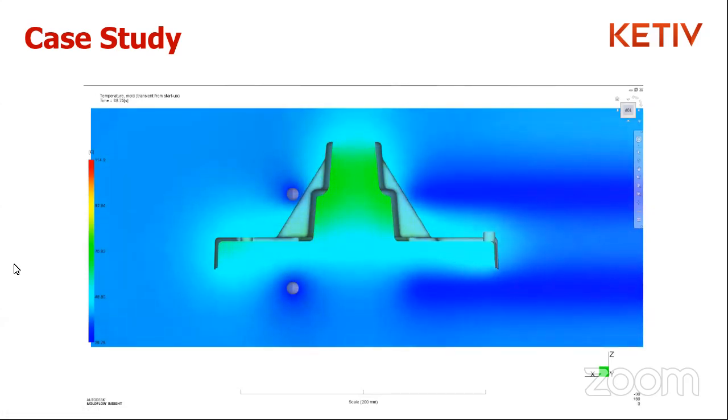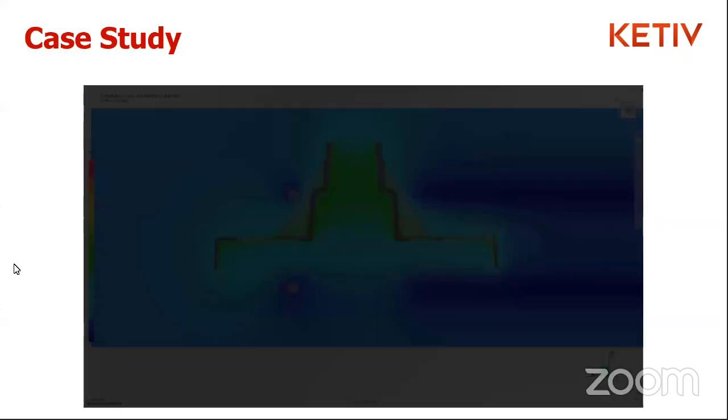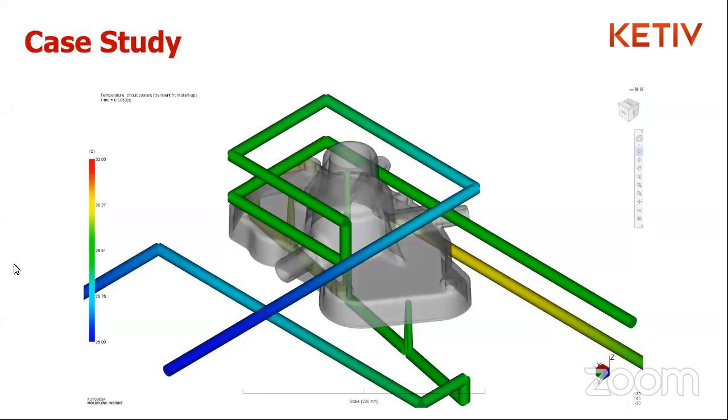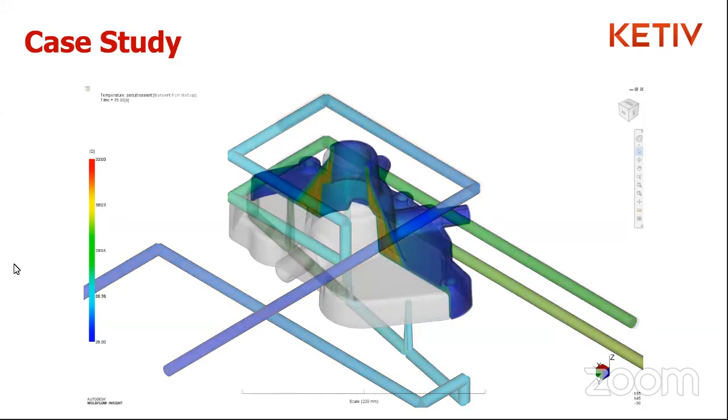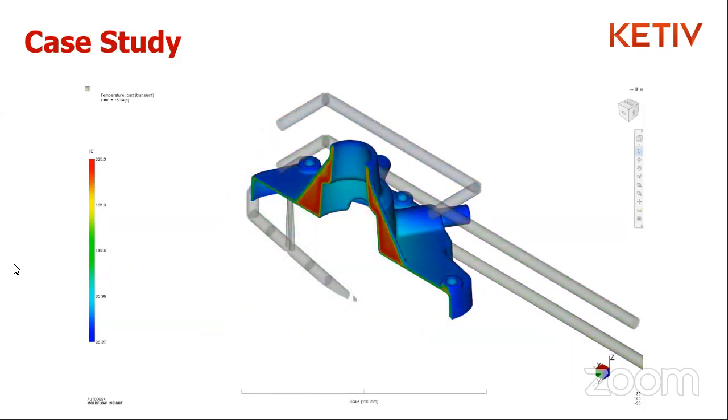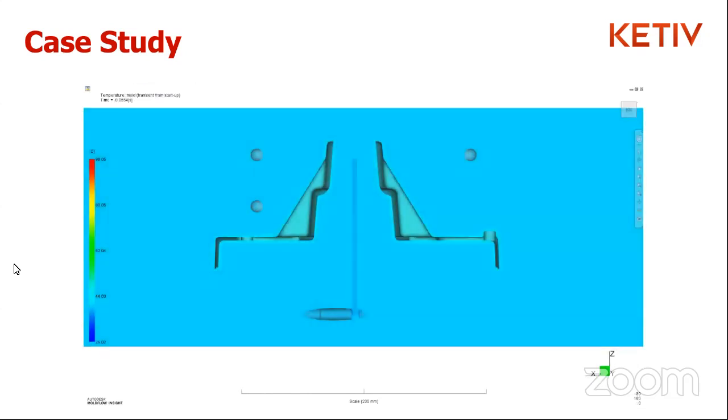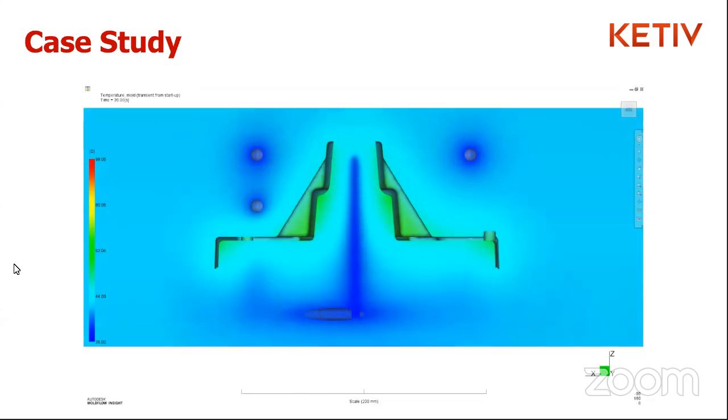If we were to test, let's say it gets slightly more complex and you start to use a more complex cooling system, right? So this is more realistic, it's more machined. Essentially, this is like a conformal cooling channel, or set of cooling channels, but it is still limited by channels actually being machined in, right? So even though this is slightly better than the oversimplified version in the previous slide, this still is not ideal. We still have some irregularities and non-uniformity in the cooling.